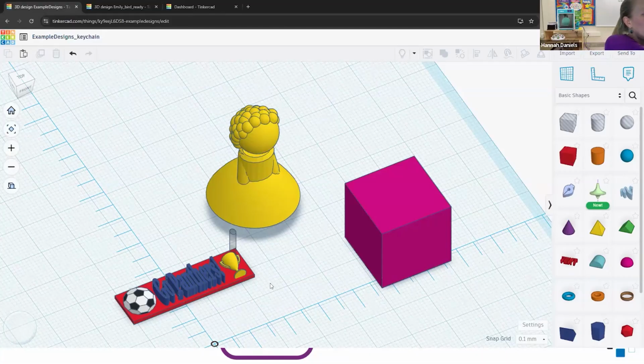Like I've got a globe of Mars here that has a full circular bottom, and yes, it has some scratchy-ish surface on the bottom that I can feel. You can't really see necessarily coming through the screen, but you can sand 3D prints. There are liquids that I've never tried that are supposed to smooth some of these things out. But there are ways to make supports work. Either way, if you can design something to not need supports, all the better.